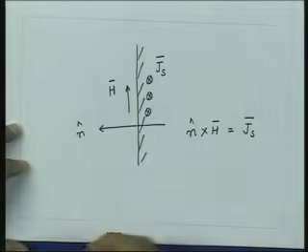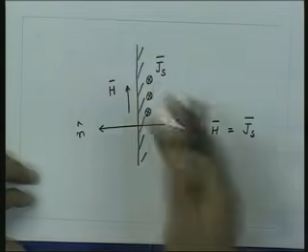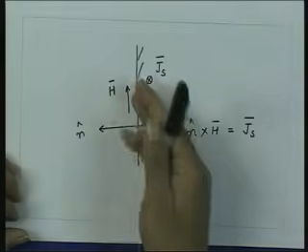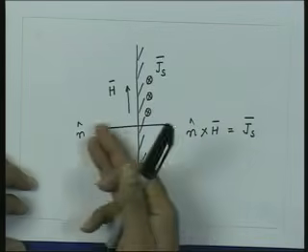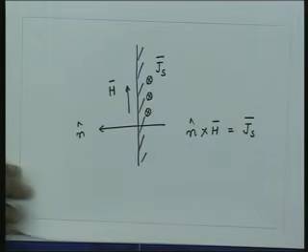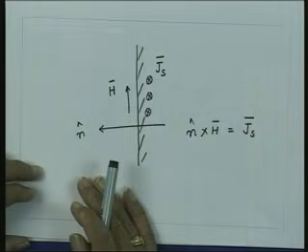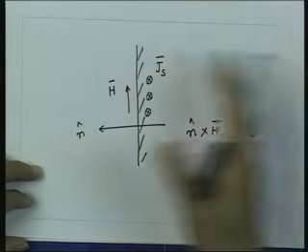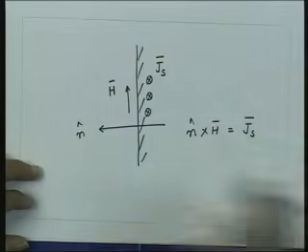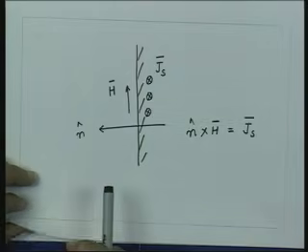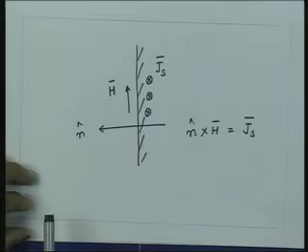We can find the same thing by an alternative approach, and that is the wave approach. What we argue is that if there is an electric field and a magnetic field on the surface of a conductor, they essentially constitute a wave phenomenon going in the z direction. So, the power which goes with this wave inside the conductor is the one which is lost in the ohmic losses of the conductor, because the medium is infinite and this power decreases as the wave travels, and no power is coming back.